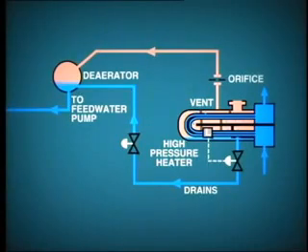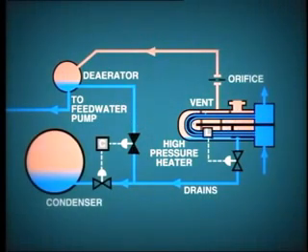However, in the case of this high-pressure heater, both the vent and heater drains are piped to the de-aerator, which of course operates at lower pressure. In many plants, this differential is insufficient at low load to create the flow of drains from heater to the de-aerator. Remember that in many plants, the de-aerator is located at a high elevation. To avoid this problem, the high-pressure heater drain can be alternatively routed to the condenser by automatic operation of control valves.